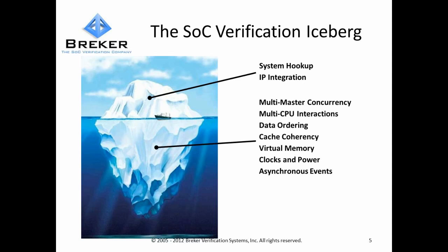We've got to focus on multi-master concurrency, get all those IPs running at the same time, get multiple CPUs interacting with each other, sharing memory, making sure they're coherent. We've got to worry about data ordering across the network on chips. We've got to worry about cache coherency, power management, asynchronous inputs, lots of stuff.